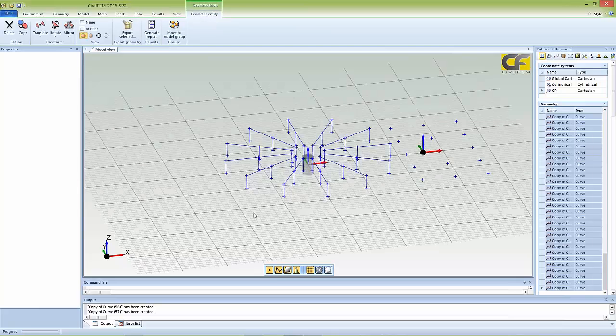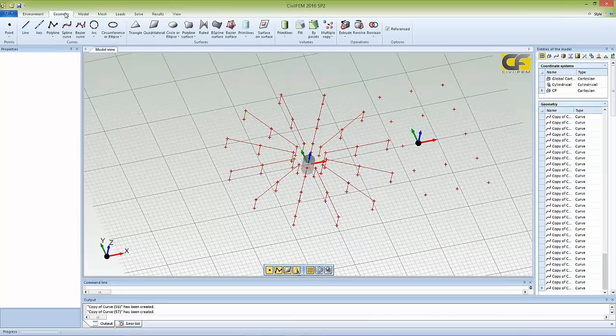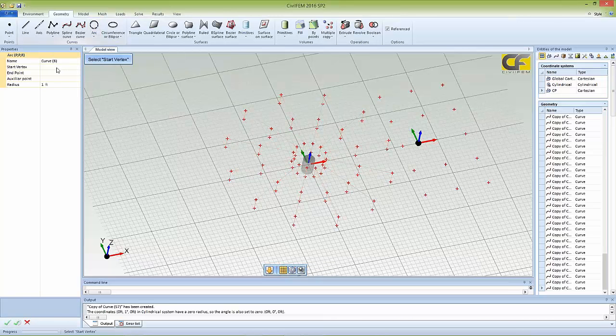Now we're going to draw the curved beams for the floor of the second floor, which will be the ceiling of the first floor, or ground floor. There are several options. We would choose to have 3 points around the circumference and its radius. The first 2 points belong to the segment for which you're going to create the arc, and the third one defines the direction of the curvature with a given radius.